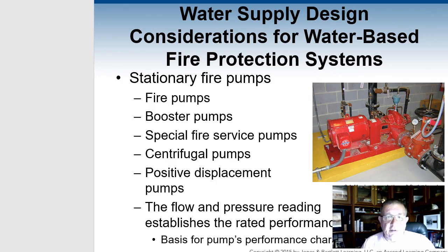Stationary fire pumps, you'll find those in buildings that need booster pumps in them. They're stationary like that. This pump is about the same type of pump you have in a fire truck, and you've got to understand that this pump is going to thirst for water. It's there because one thing is supplying the sprinkler system of the property, and more than anything, it has to have the right amount of water to feed it. So it's calculated once again by a fire protection engineer, to see how much water is coming off the fire main, so that it can feed the fire pump to feed the sprinkler system.